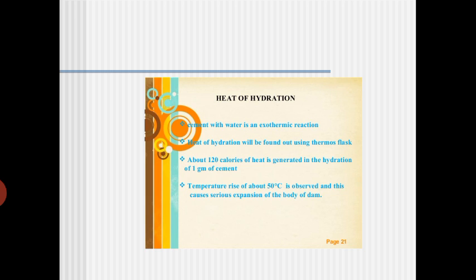But here, if many impurities are there, we will use one very specific instrument, and that instrument will give you the correct value of heat of hydration. If you are getting a standard deviation or error of more than 3 or 4, we say that it is contaminated. Up to a standard deviation of 3 is permitted in the heat of hydration.